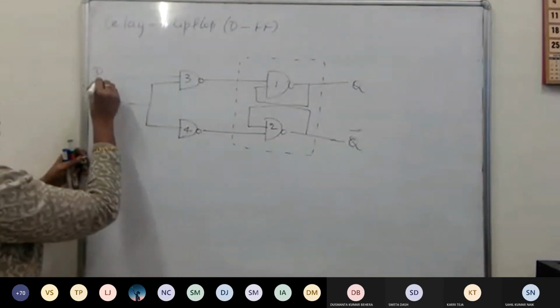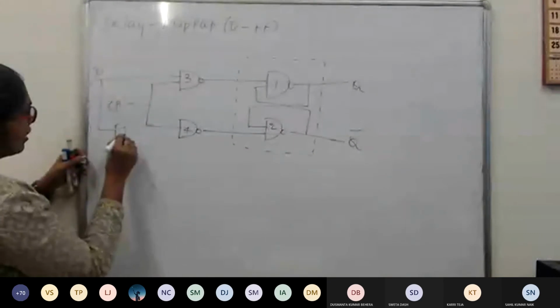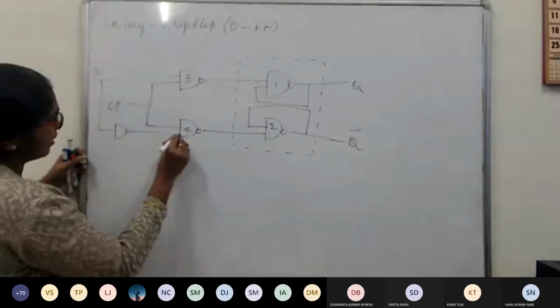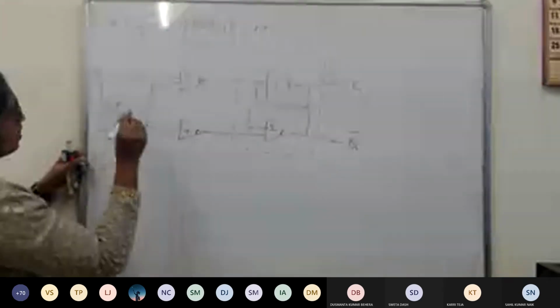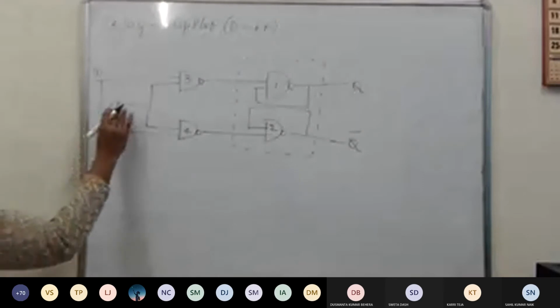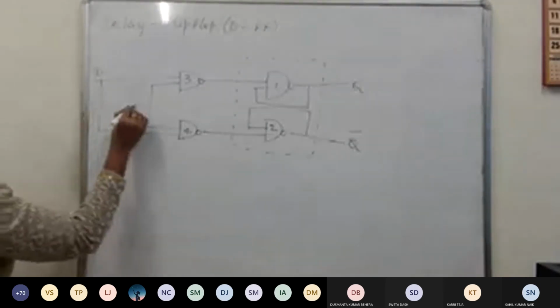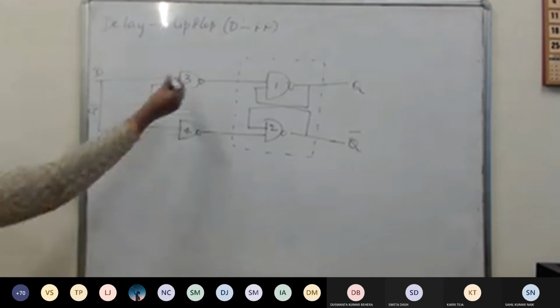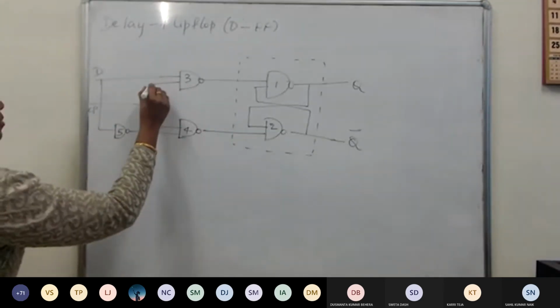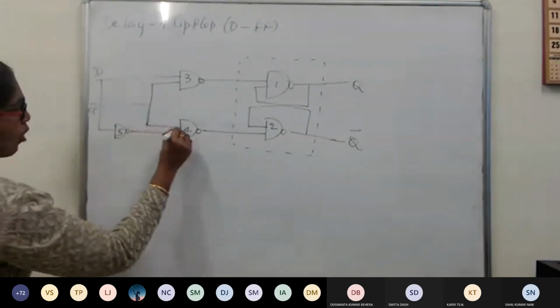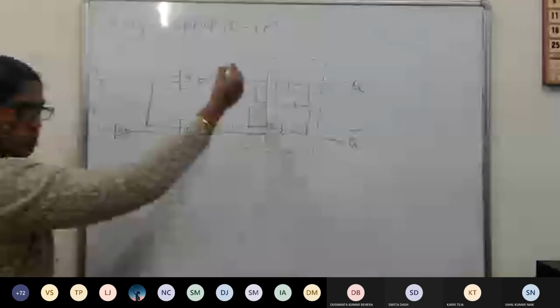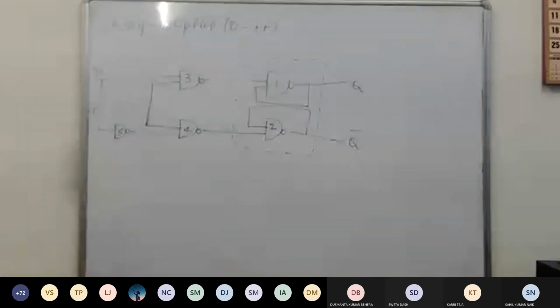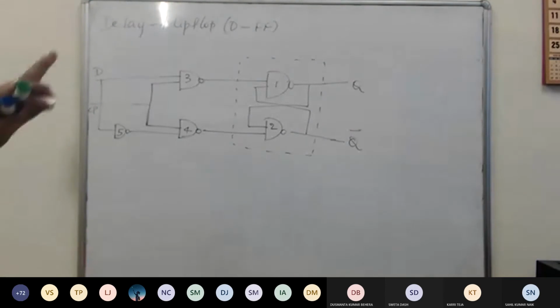Now, this is your signal D. Now, this is called the clock pulse. Now, carefully understand. This is the extra addition. This is just a modification of your SR flip-flop where a NAND latch is used. When a NAND latch is used, a little bit of difference is there in the execution. But anyway, that's very easy to understand.